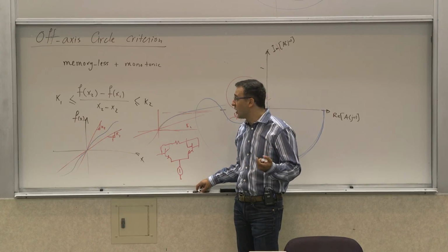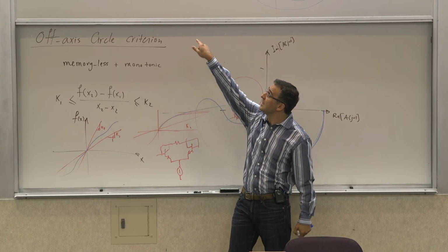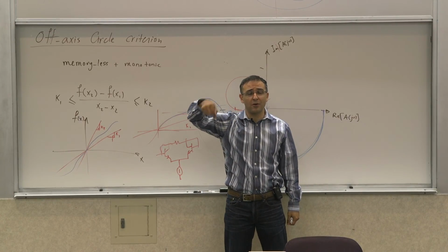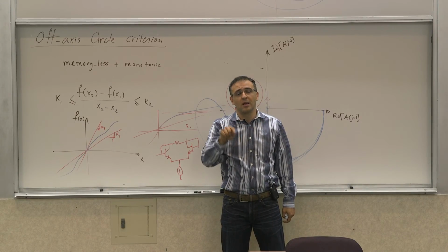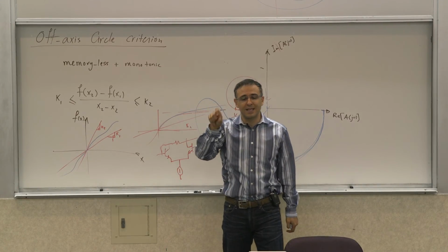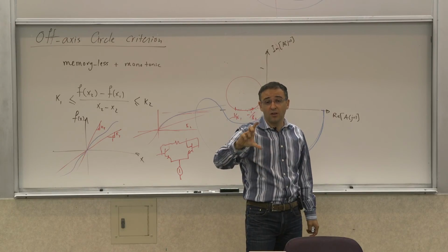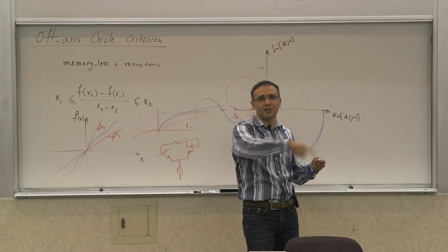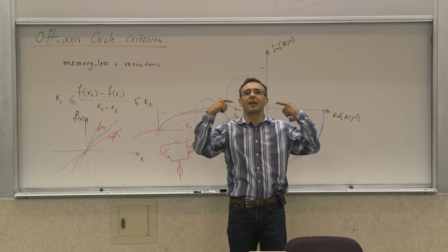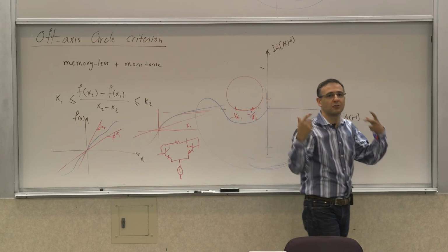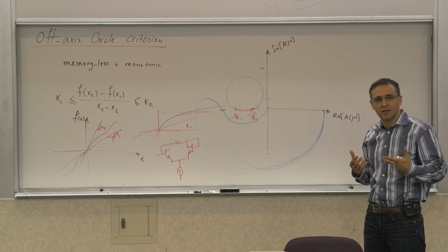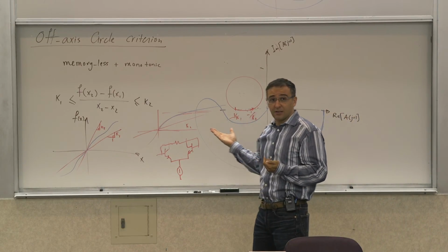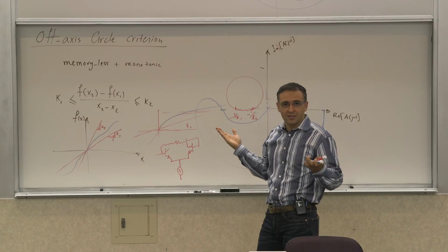In fact, we saw that we can have systems where what comes in and what comes out of the loop when you break the loop is exactly the same phase as what goes in, and it's larger. So you would think that if I put this in, it's going to grow, because what comes back is larger and goes through again. That's the wrong image. That's an incorrect intuition about oscillation, because we saw a clear example of that not being true in the conditionally stable system.